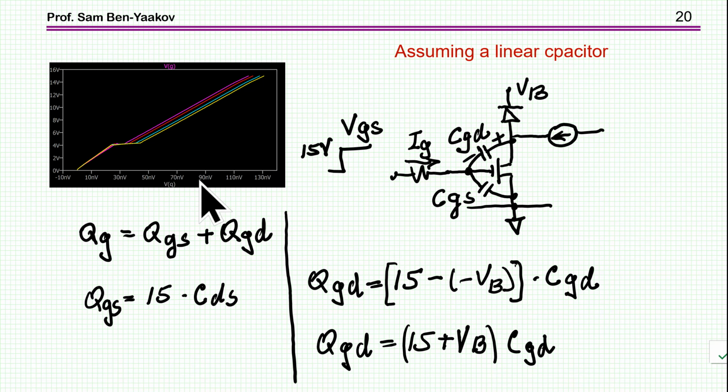Now, Miller effect talks about an impedance between input and output of an inverting amplifier and how this impedance is seen when looking from the input, which is a similar situation, only we are talking here about a nonlinear effect, so it's a little bit different. So let's see how we can explain what is really happening here while we are changing the input voltage.